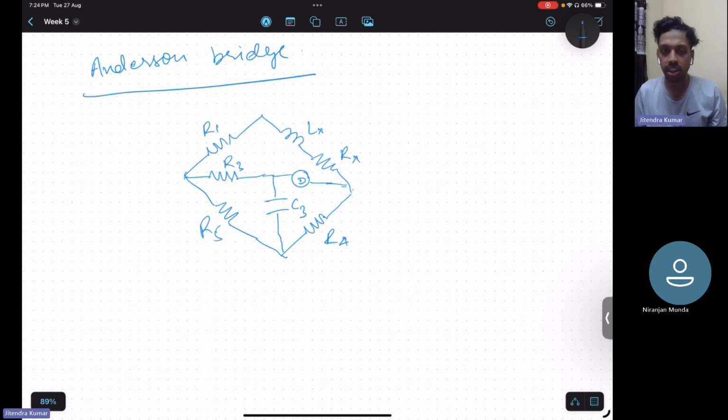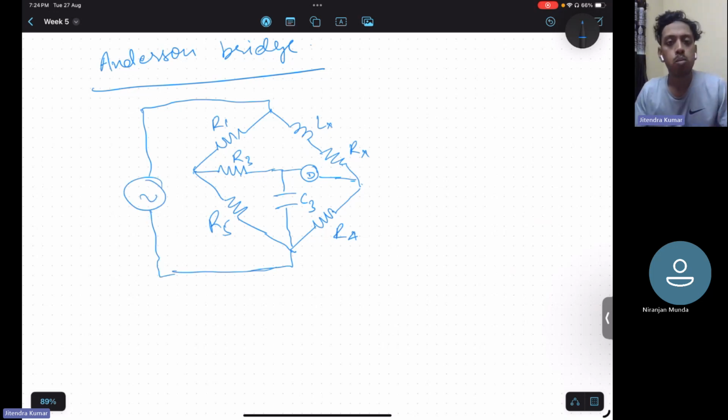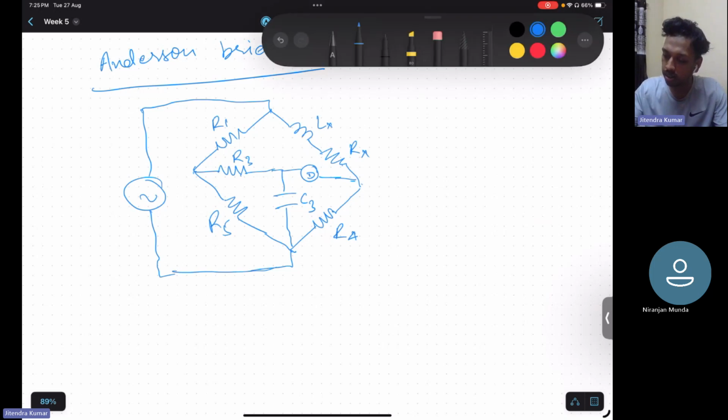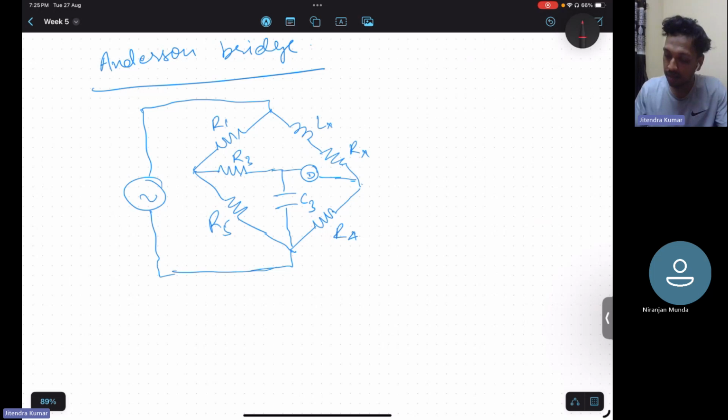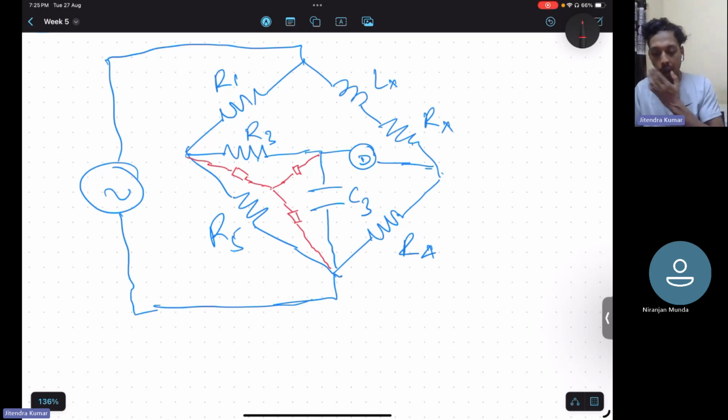Okay, so this circuit looks a bit complex. Some AC supply is there. But we are used to solving straightforward circuits where all the branches are diagonally opposite connected. So here also we can make it like this. We just need to convert this delta circuit parameters, which you can observe here, into a star. Then you will have the earlier, conventional circuit.